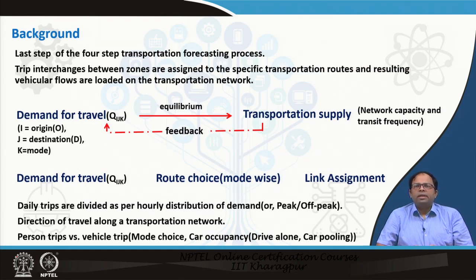And in that way we can determine that during off peak hour maybe 40% of the total load is concentrated within maybe 4 hours or 5 hours, whereas morning 2.5 hours, evening 2.5 hours, whereas the rest 60% is spread out all throughout the day. So in that way we can also decide.